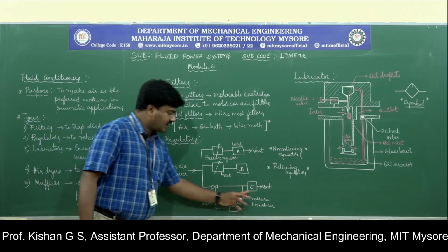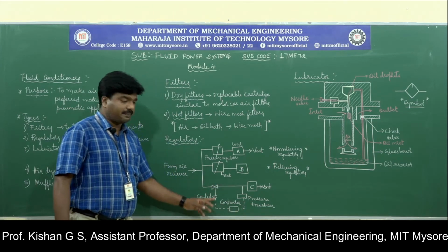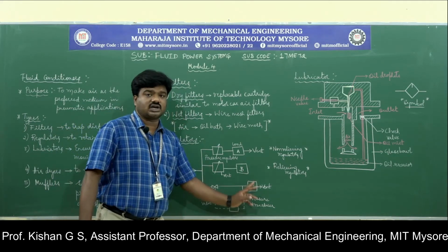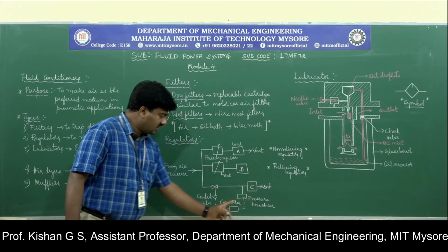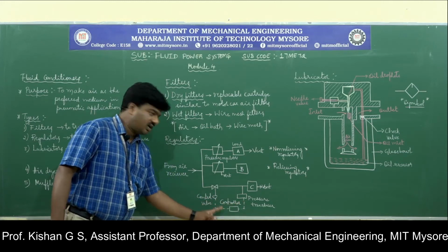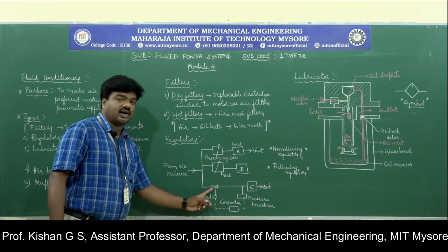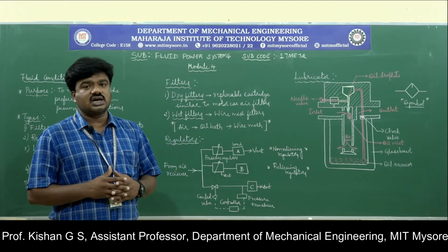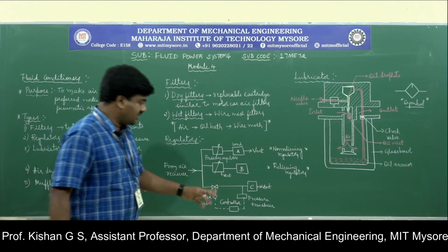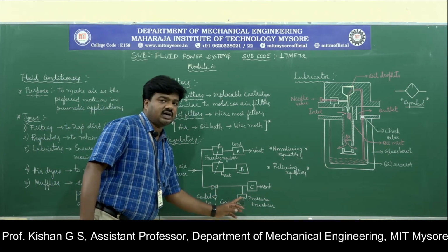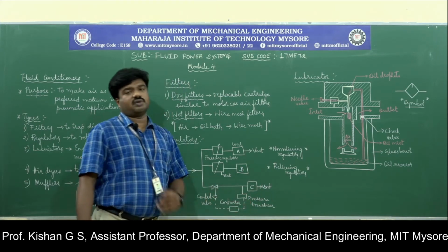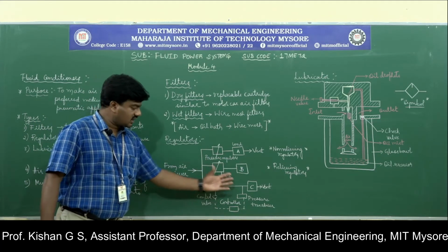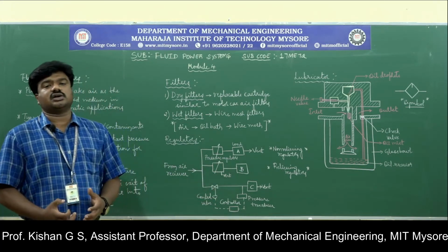Okay, if the pressure transducer identifies that the pressure at which the air is coming from the receiver is greater than the pressure required to perform the work, then it sends a signal to the controller, wherein the controller activates the control valve and results in the exit of the pressurized gas from the system, so that the necessary amount of pressurized gas will be taken into the load C to perform the particular work. It is similar to the relieving regulator, but it is completely controlled by the electrically controlled system.